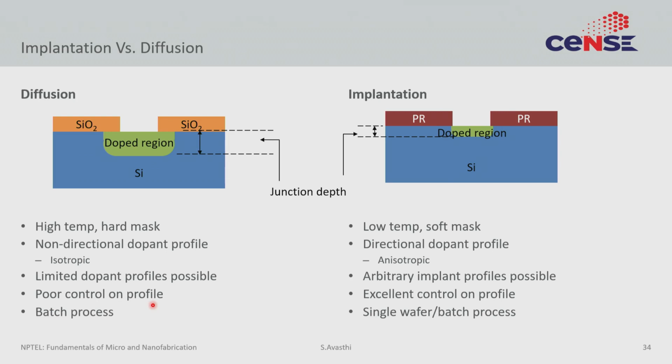If you remember, we discussed a two-step process. The reason we needed a two-step process was that it was very hard to exactly control the diffusion profile, to get exactly the same peak concentration and exactly the same depth, all because it's a process that is very hard to exactly control. Ion implantation, on the other hand, is much more accurate. The dosage can be measured with arbitrary precision because it's equivalent to measuring charge or measuring current, and we are very good at that.